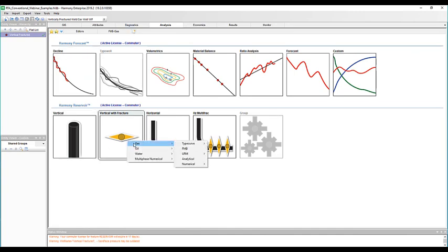Now, similar to pressure transient analysis, type curves are great to help identify flow regime as well as getting your key parameters such as your permeability, your skin, your fracture half length, and remember they're dimensionless models between the reservoir and the well. So we're going to start off with the Blasingame type curve. We've taken a look at the theory behind the Agarwal-Gardner, the Blasingame and the Fetkovich type curves in a previous webinar.